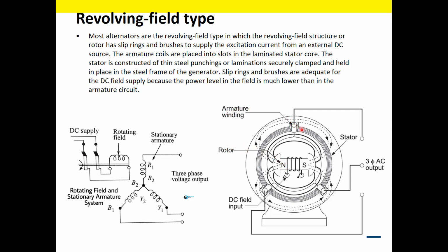Okay, we have our rotor here. We have our armature windings. Okay, they're stationary and they're situated 120 mechanical degrees apart from each other, and they're going to generate our three-phase AC. When the magnetic field starts to rotate, like we had that little animation there, the magnet rotates and it's going to induce three-phase electricity, each phase 120 degrees apart from each other electrically, because the windings are mechanically apart from each other.